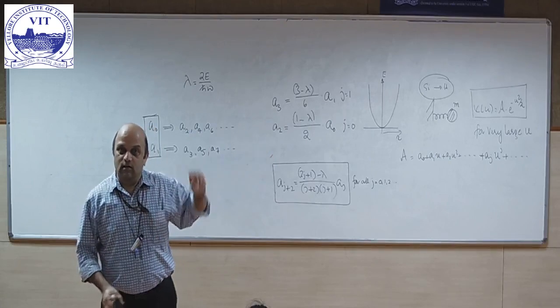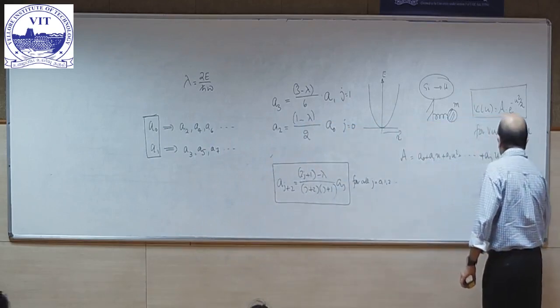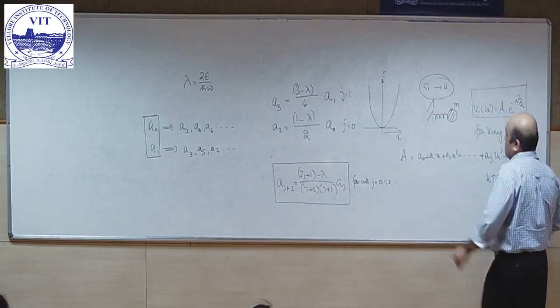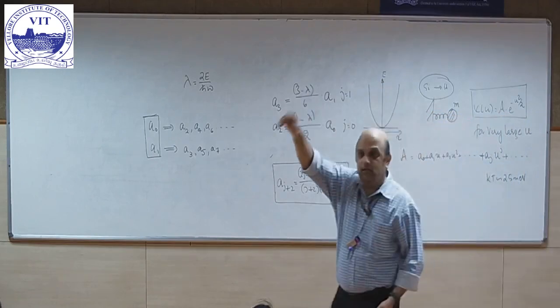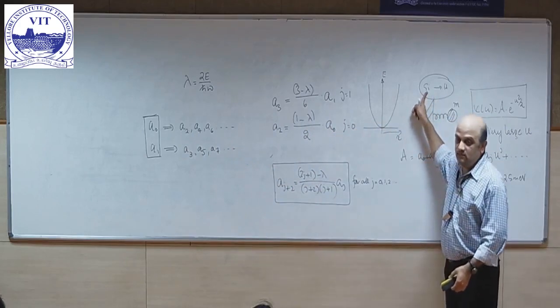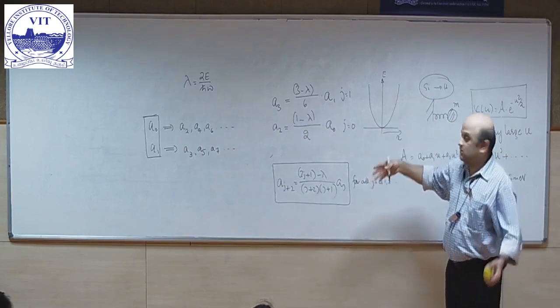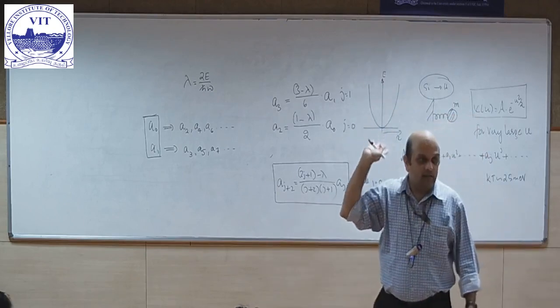So that means the kind of energy levels it can have as a harmonic oscillator are limited. Okay? kT is almost 25 milli-electron volts. So this energy is only 25 milli-electron volts. Beyond that energy, this hydrogen atom dissociates itself from the silicon atom. So there is no harmonic oscillator. That means you do not need to consider energy levels beyond that particular value.